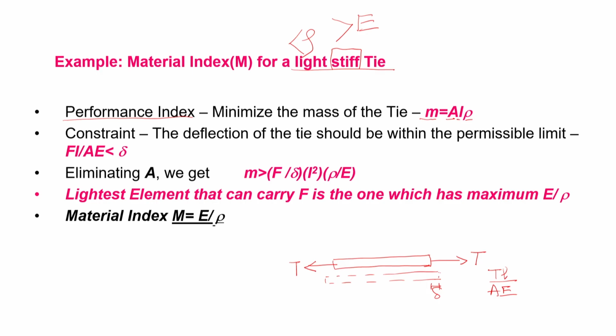Okay. Now, I know this much, fine. So, now I am looking at what is then my mass? Well, in my mass we have area of cross section, we have length, we have density. Length of a tie cannot be changed because it is connecting between two members. Density we are looking for. So, it is the area only which is the free variable, that is very important. So, that means area from this particular relationship can be written as what? M by L rho. Area is that free variable.